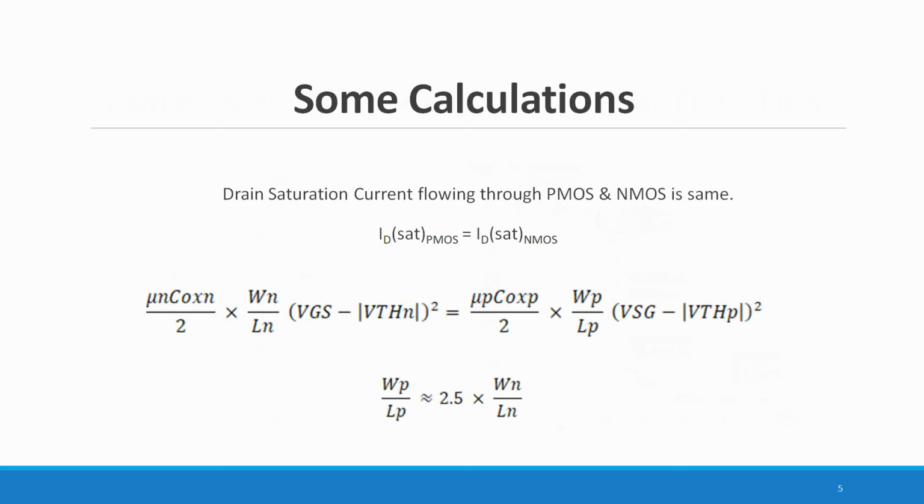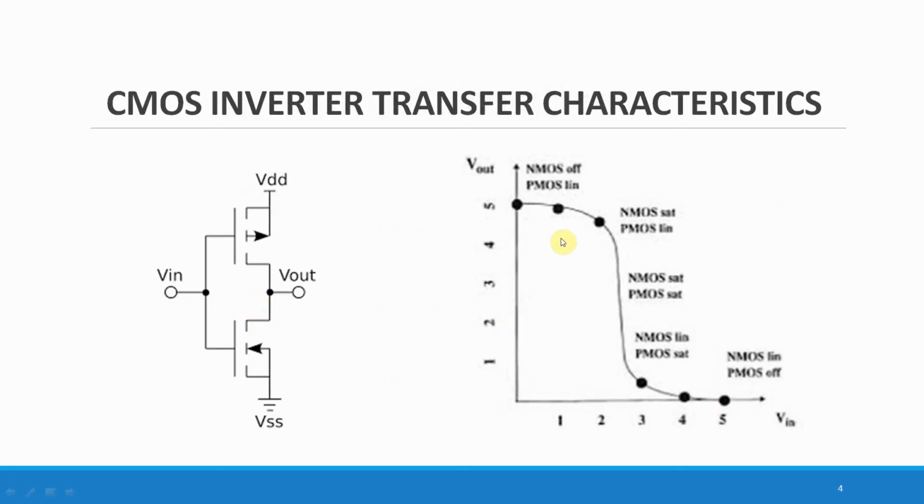So that's the reason the voltage fluctuates in this manner, because the width and length of the channel and the oxide capacitance all play a very crucial role at the fabrication level, and minor changes in these can create a huge difference at the output stage.